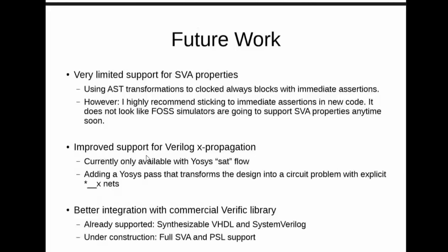Okay, future work for this kind of stuff. Right now there is very limited support for SystemVerilog assertion properties. I'm going to extend this a little bit. It will still be far away from the whole SystemVerilog properties feature set that the standard describes. The primary goal here is to define a useful common set between the things that Yosys can do and the things that most commercial tools can do, so that you don't need to write different properties or different formal test benches depending on what kind of tool you target.